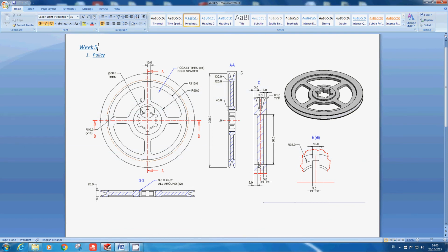Now I'm going to go across to this view, because the remainder dimensions I need are here. They're all in this view here, so I can focus on this one view from now on. So I'm going to draw everything you see, basically. Anything that isn't cross sections is actually cut out. You can see it. I suppose it's easy to see when you have the 3D view here, but again, from the cross section that we've taken, we know that this isn't in the part. We know that this is a cut. So I'm just going to draw the two of these, left and right. So dimension 5 and dimension 80, and they're symmetric about the origin here.